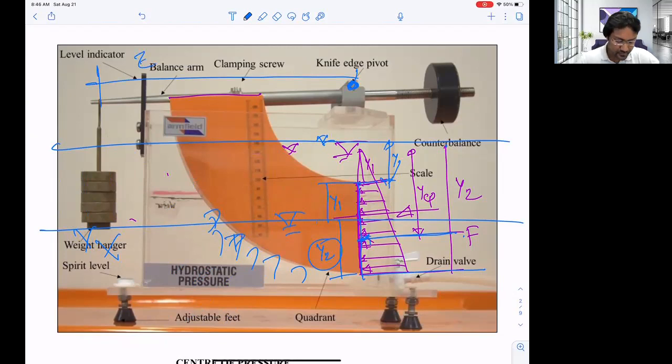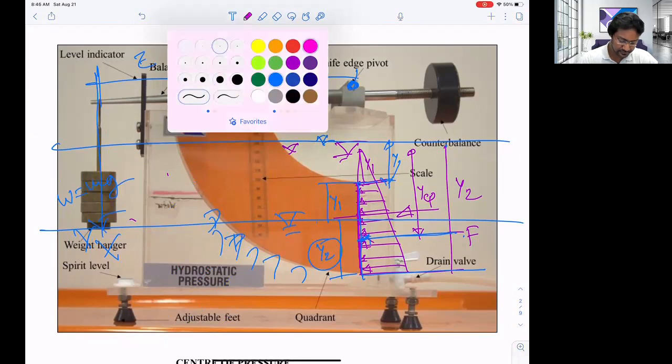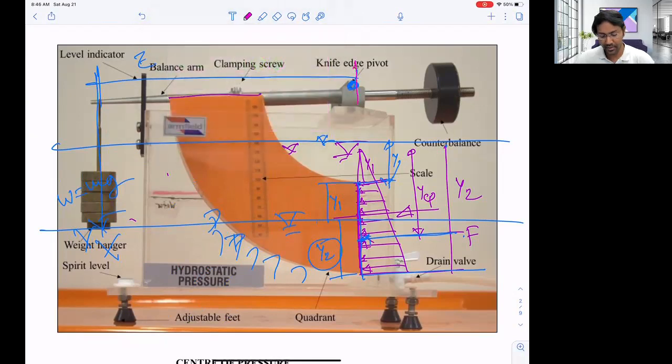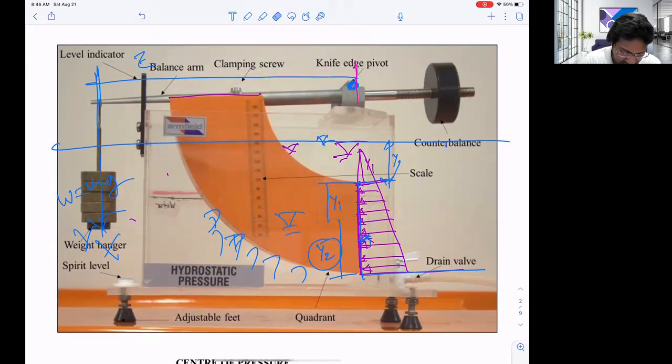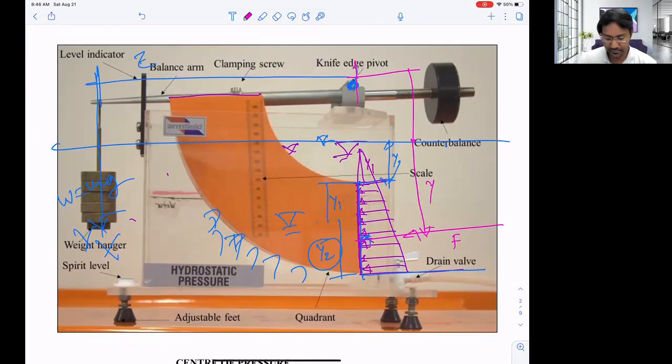So once we have the balanced system, because that is the hinge we have, and we have this weight, we know that distance is G, as we just demonstrated before in the practical application, right? We already have an idea. When I calculated the stability of a dam, we used this G, and this G is from the hinge to this one. W is equal to mg, okay? And then, from this hinge, we have to calculate the distance of the center of pressure, right? Let me quickly remove all this. I'm considering that is the center of pressure, that is F, the total force acting, and from this we're calculating this distance y. So we have F, the moment term y, and we also have this g, and this mg.